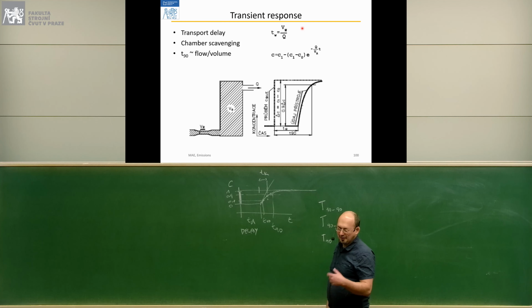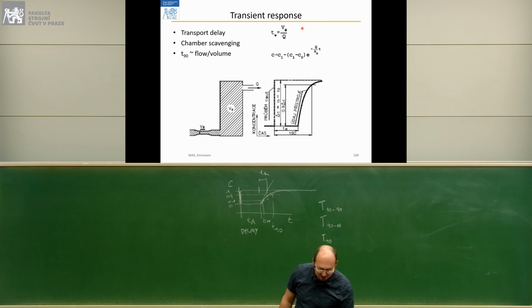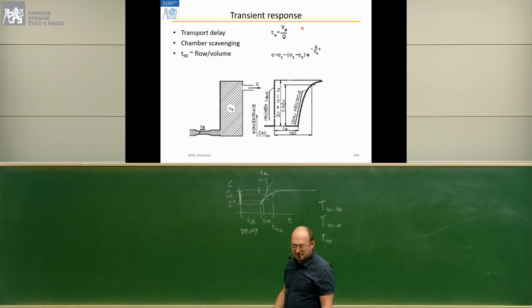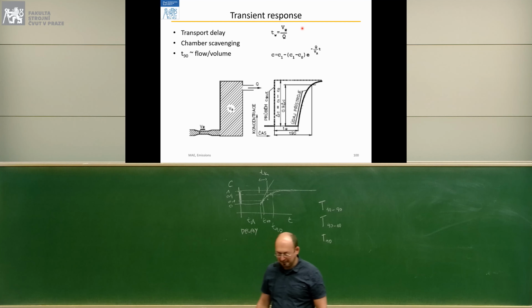Especially with optical analyzers, or any analyzers that are sampling into some volume, as the volume is being scavenged, the new sample is replacing the old sample.